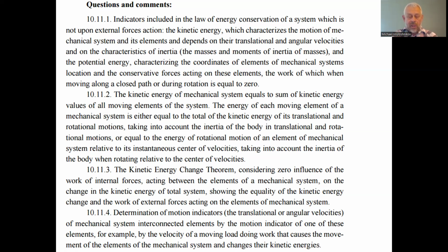In a more general approach, the kinetic energy in the plane motion or in the spatial motion, that is in space, equals the total of the translational motion of the center of the mass of the element of the mechanical system, or the total mechanical system, and the rotation of the mechanical system around the center of the mass. Or we can consider, instead of the center of the mass, the instantaneous center of the velocities.